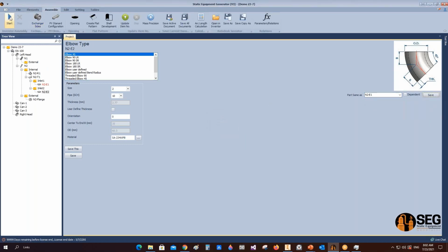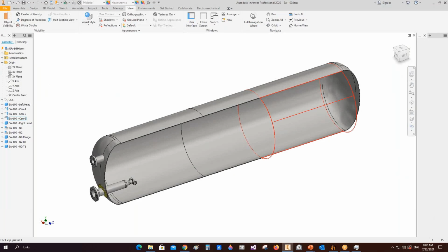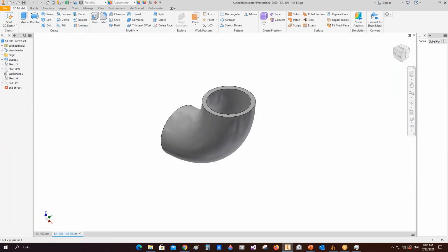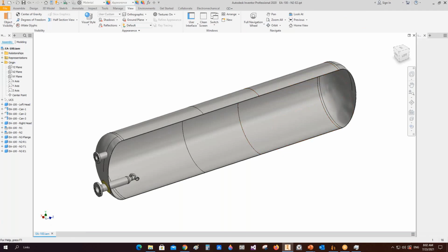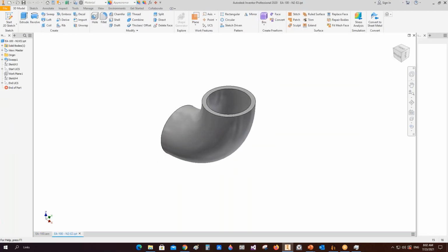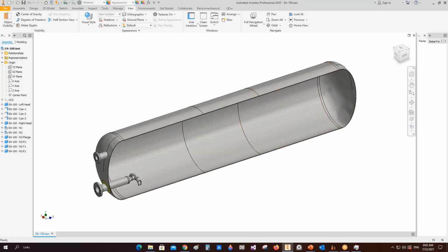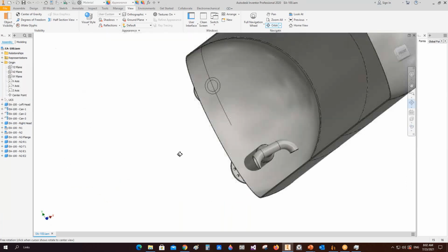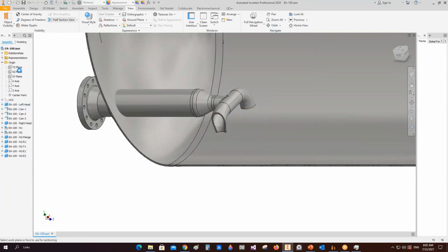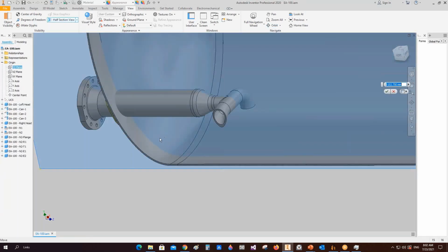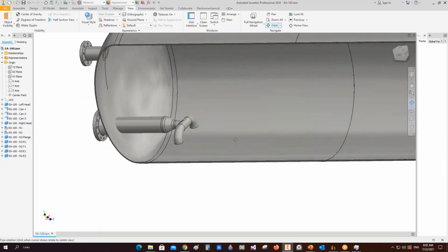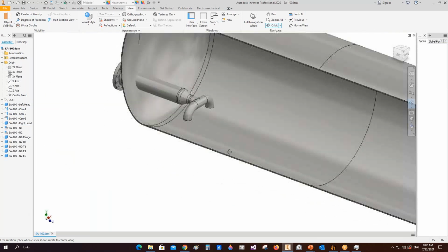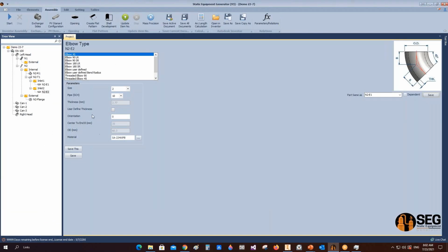Okay. Now if we click on the assembly button, we will create two elbows. Each one of them will be at the end of the T. Okay, now we have those two elbows right here, like that. And if you would like to control the orientation of them, you can do that by controlling the orientation of the elements.